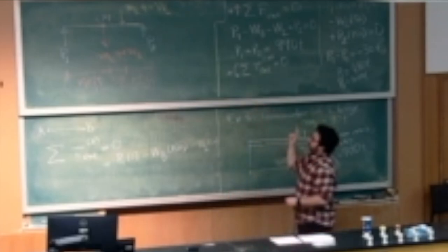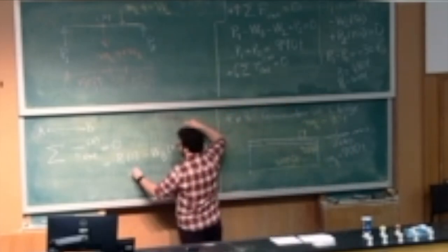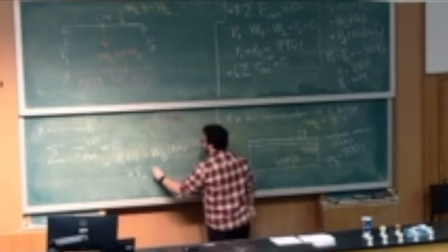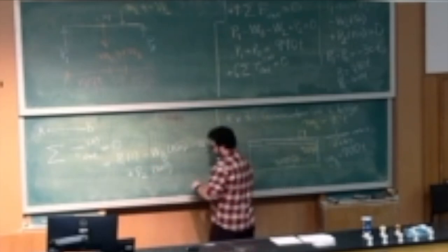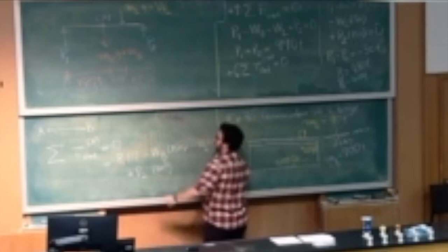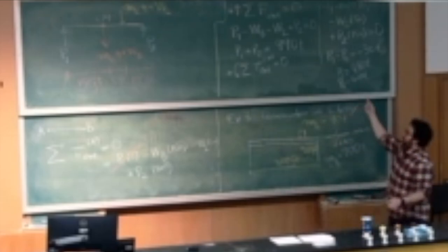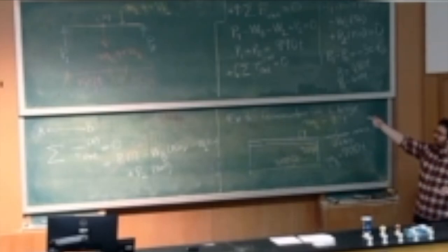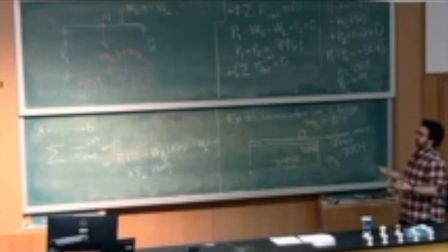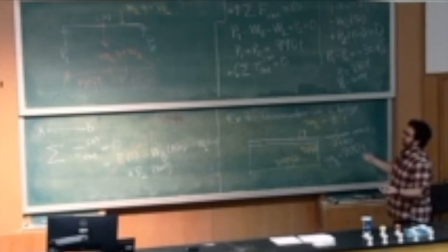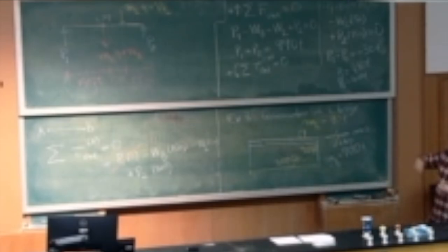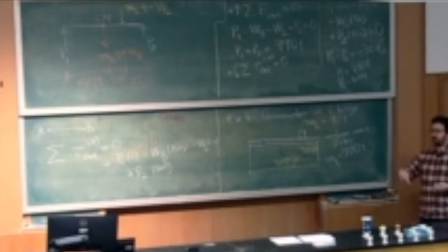And we have this P2 trying to create a counterclockwise moment with the entire span as the moment arm, so we have 300. So this is 0. And you can easily solve this equation for P2 now without having to worry about two equations. You don't have to do that. It's not a must. You are not required. But sometimes when you have more forces involved, this is how you could simplify your starting equations, so that you have fewer equations with fewer unknowns, so you can solve them in a faster method, especially during exams.